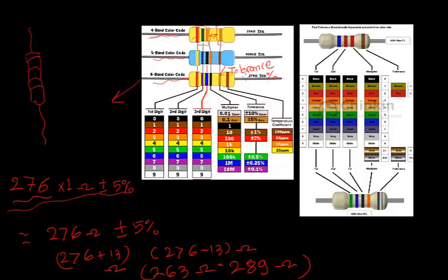So the question is, what is this last band, right? This last band is brown, which talks about the temperature coefficient. As you can see, this band is not present in these two resistors because this band is not mandatory, it's not always there. And this band is the temperature coefficient, which is expressed in parts per million. Okay, so the same example is shown here.